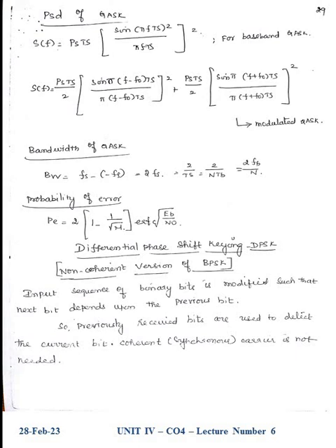When we compare DPSK and BPSK or PSK, there is an ambiguity of phase modulation. When we rotate the constellation points, it affects the communication channel through which the signal passes. That problem is overcome by using the data to change rather than a set of the phase. So that is why we are going for differential phase shift keying.